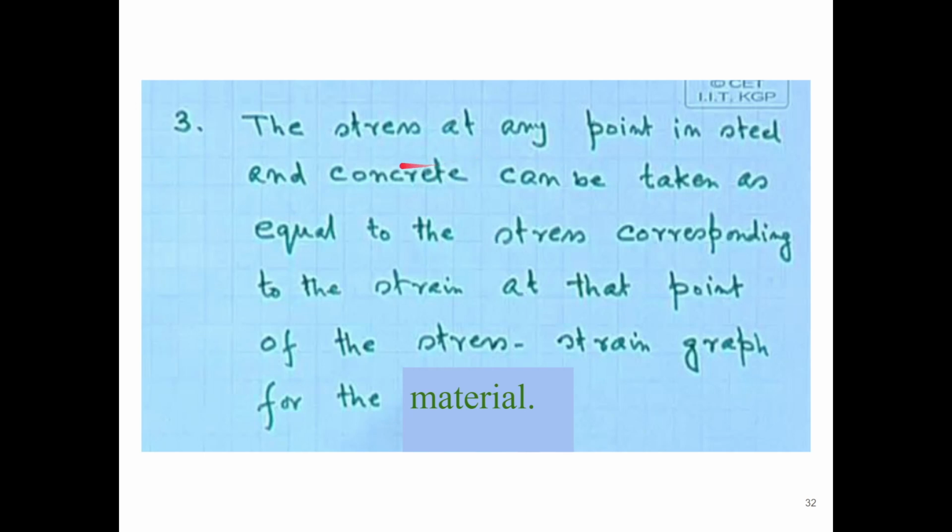That was having a value of 0.87 fy by Es plus 0.002, right? So that was the maximum value, but this epsilon sc value will be lesser than that. Based on that point, from the stress strain graph for that particular strain, we have to find the stress for the steel in compression, which is fsc. So this consideration is required.